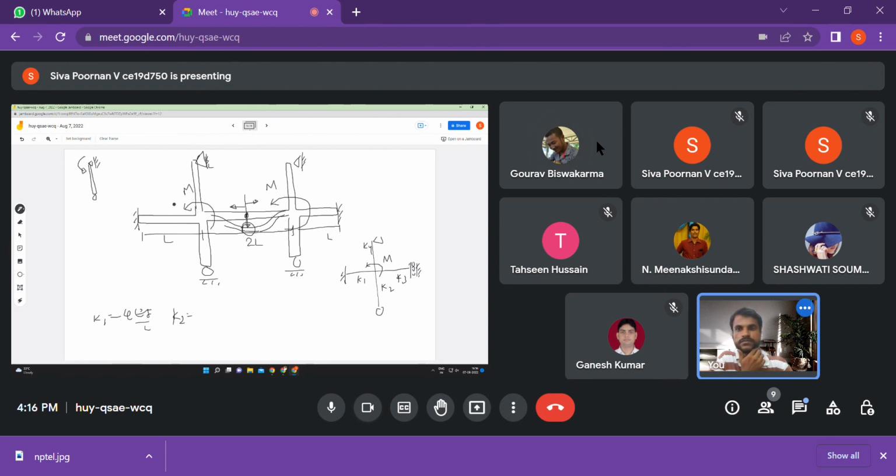Okay, fine. So what will be the stiffness of the system? Since it's a roller, it just moves, right? This is possible only because it's perpendicular. Let's say you have a roller and a perpendicular member like this, then it doesn't resist this motion. That's the whole reason. If it were inclined, if I had drawn a roller here, then it would also be 3EI by L, like a simply supported beam. But the roller is not there, the roller is here. So K2 is zero.